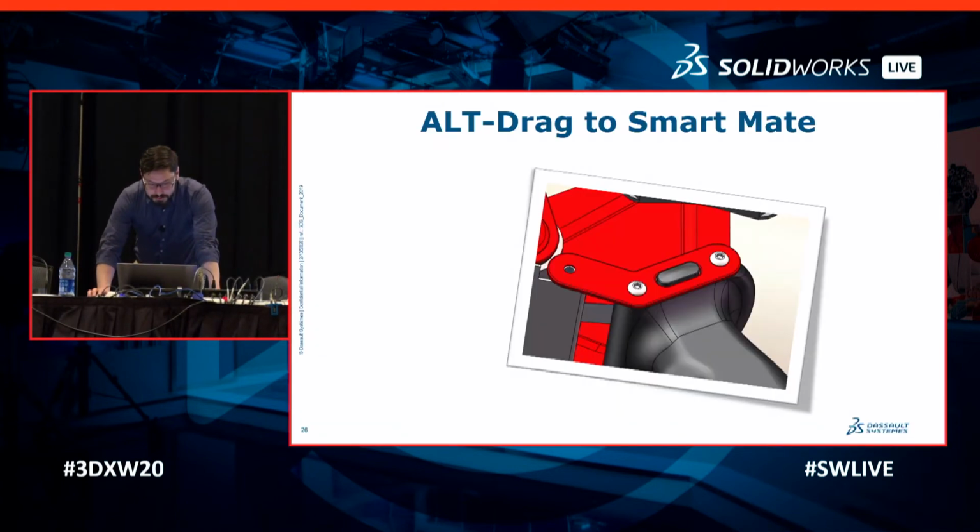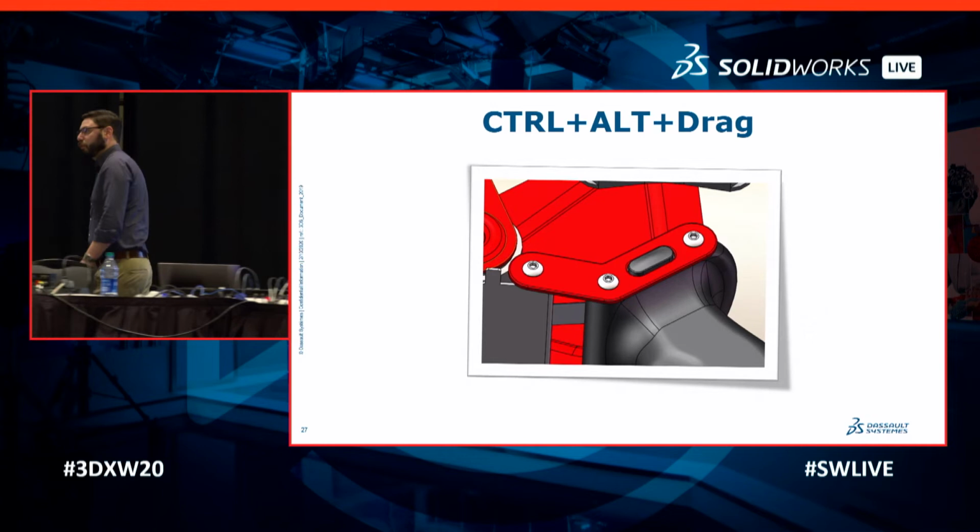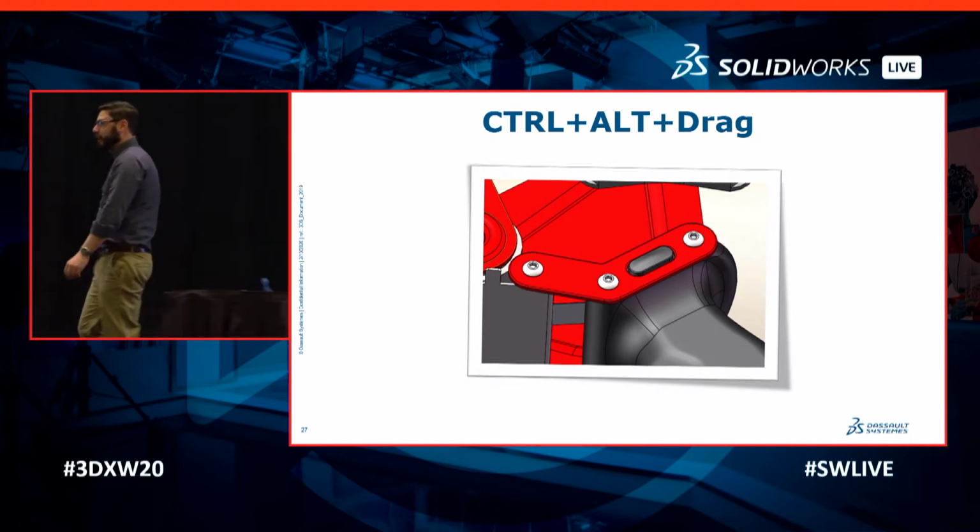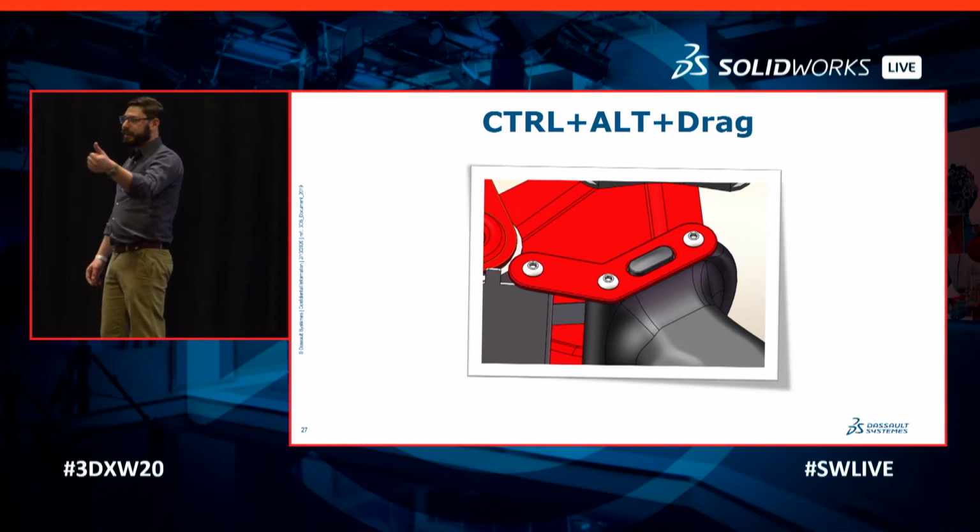Now you can combine those two. You can hold Control and hold Alt, and then drag that part, and it will both copy and mate the part.